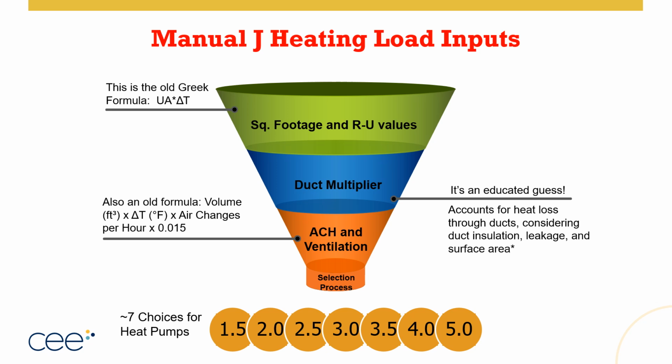So this stuff is getting more important to get accurate because we're a lot more fine-tuned. We're also only going up to 5.4 tons. That's the equivalent of going to about 65,000 BTU on the other scale. So we may actually need multiple heat pumps within these range capabilities to do what we could have done with a single gas furnace before. So it does start to make sense to really get this information as accurate and as reliable as we can. It's not about being perfect. Perfection is the enemy of the good. What we want to do is get that reliable and repeatable data.